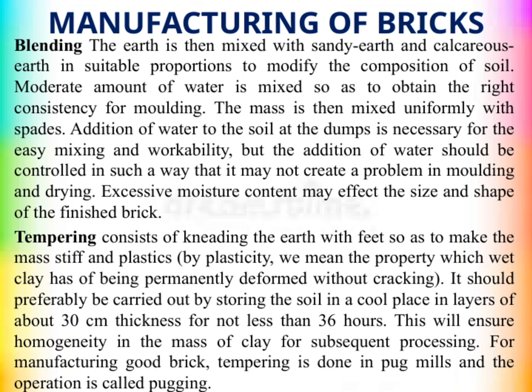This process involves kneading the earth, often with your feet, to make the mass stiff yet plastic. Plasticity in this context means the ability of wet clay to be deformed without cracking and to retain its shape. For best results, the soil should be stored in cool, layered heaps about 30 centimeters thick for at least 36 hours. This resting period helps achieve a homogeneous mixture, which is vital for quality bricks.